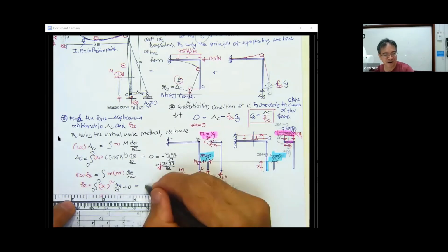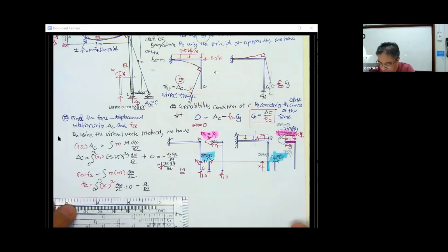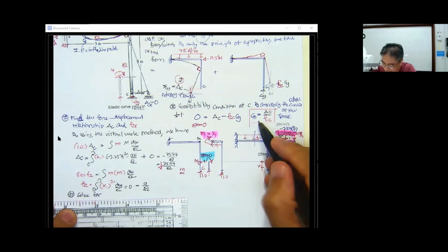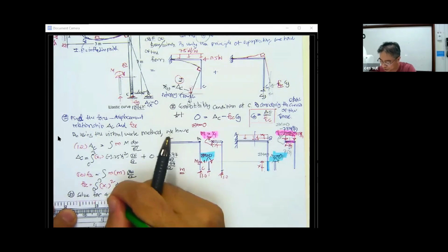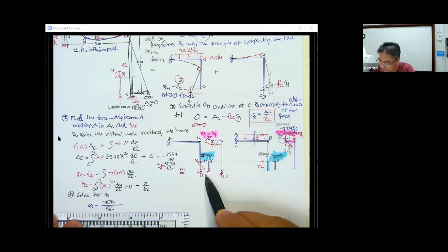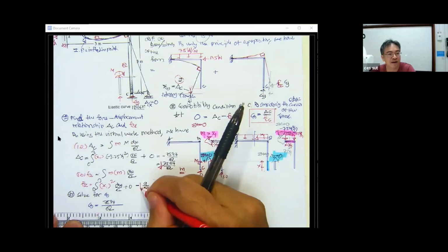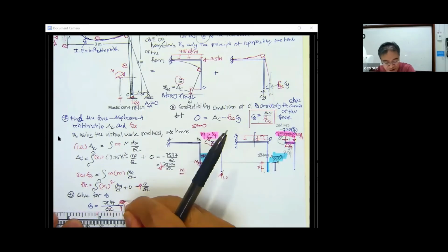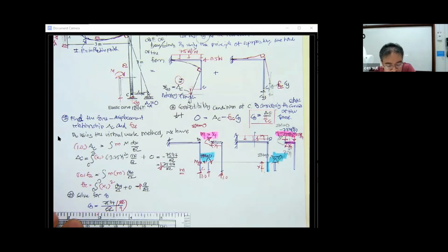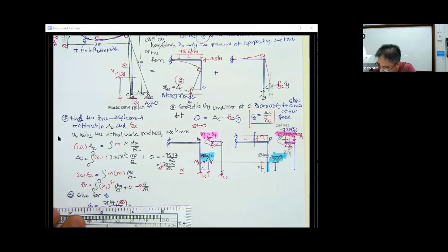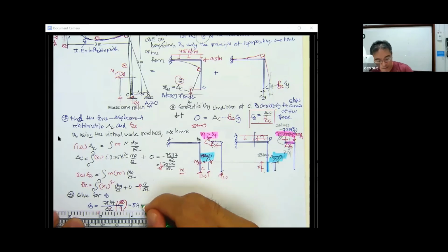Okay, and then we go further. We just go to step 4. We solve for C sub Y, and then we have C sub Y equal to 75.94 over EI. This one has the same direction as we expect from the previous consideration here. So this one is EI divided by 9. You just put this together and the result is really easy: 8.4375 kilonewton.